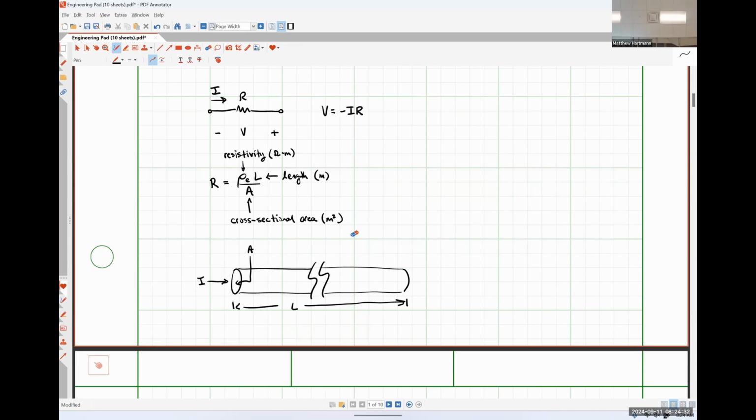This definition for resistance comes into play a lot when you're designing microstrip transmission lines and things like that for making integrated circuits, where you're using long runs of wire that have a specific rectangular cross-sectional area based on the thickness of the copper trace and all of that kind of stuff. But anyway, I want us to look at this relationship, and I want us to calculate the resistance of a section of wire like what we've used in our previous classes, okay?